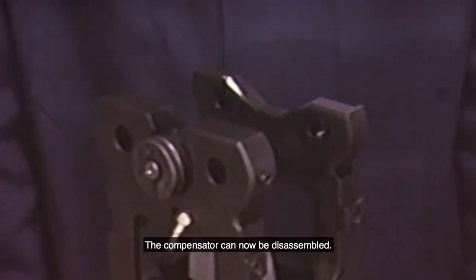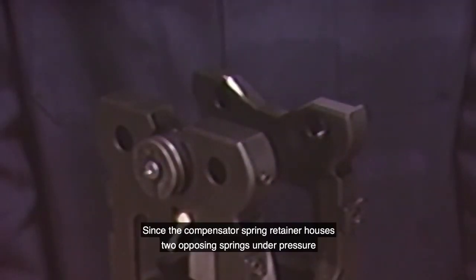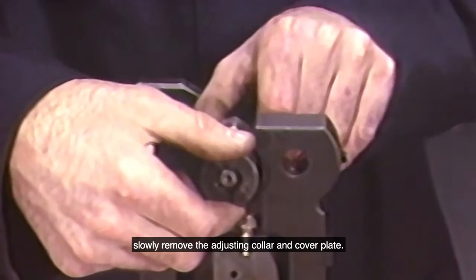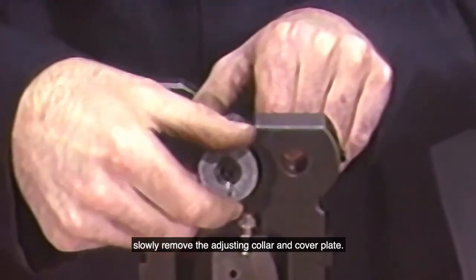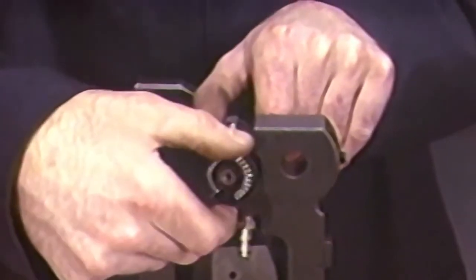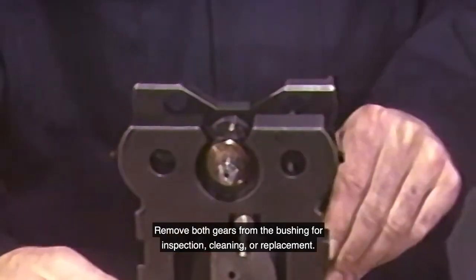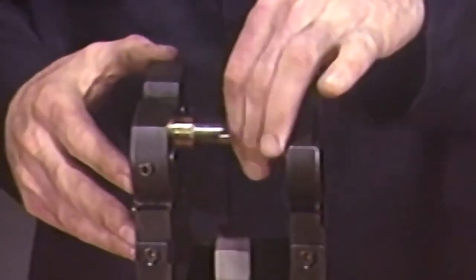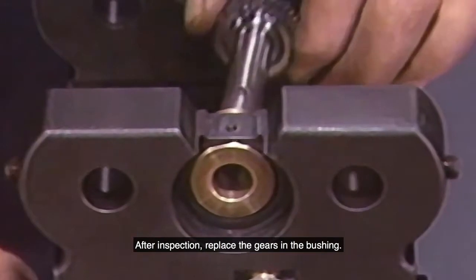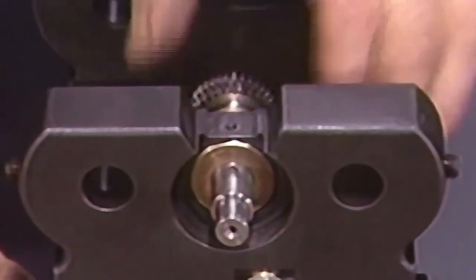The compensator can now be disassembled. Since the compensator spring retainer houses 2 opposing springs under pressure, slowly remove the adjusting collar and cover plate. Remove both gears from the bushing for inspection, cleaning, or replacement. After inspection, replace the gears in the bushing.